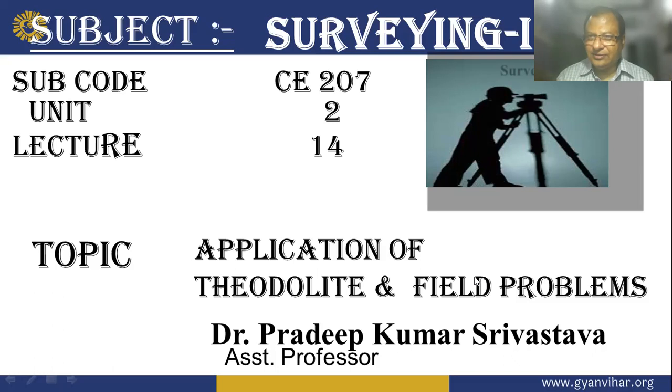You can perhaps measure distance also, but if you are using the stadia method, you have to derive the constant, and after that, with the constant, you can measure the distance. But the main thing is that the theodolite is used for horizontal and vertical angles.